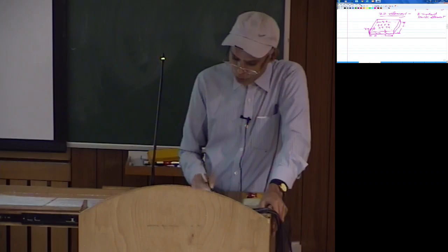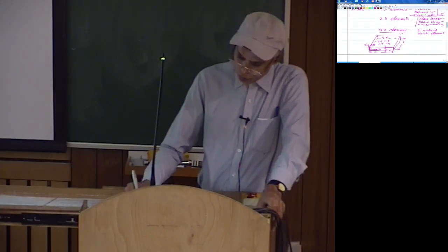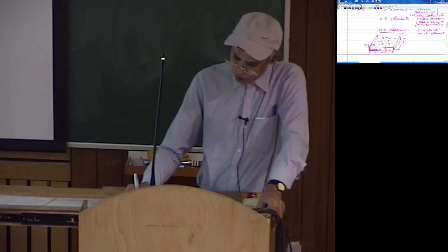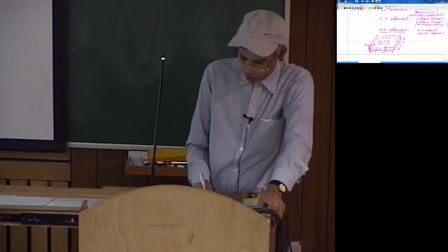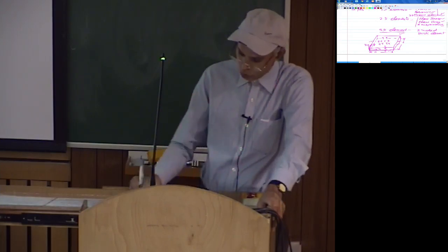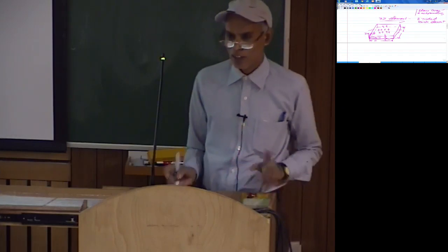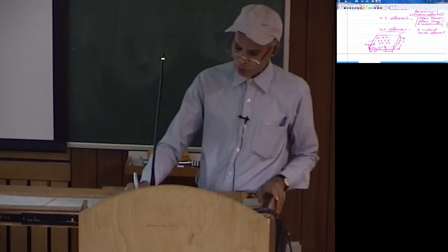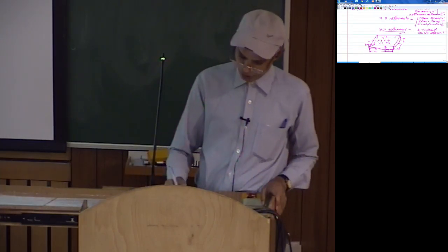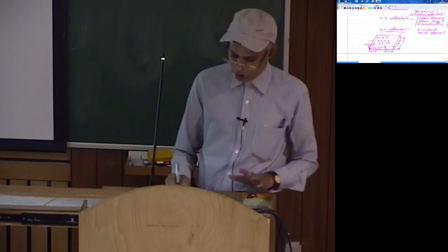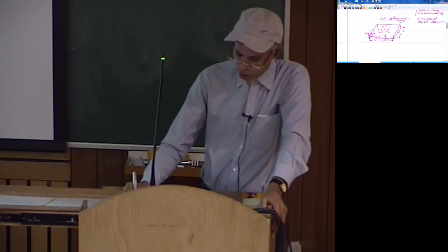So under 2D, so far we only discussed plane stress and plane strain, wherein we take only in-plane loads, that is loads in these directions. Now if there is a transverse load, such elements are referred to as plate bending, similar to the beam element in 1D. Plane stress, plane strain is like truss in 1D, and this plate bending element in 2D is similar to beam in 1D, that is, transverse load.